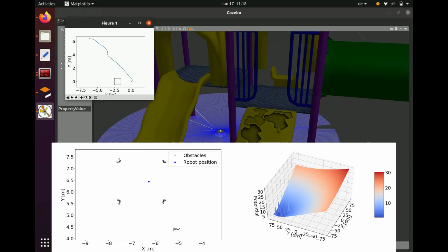It finished. Here is the last drawn potential field. You can see where the 4 poles surrounding the robot are inside the potential field. As you can see, even with a very basic implementation of the potential field method, the robot is able to avoid obstacles and reach its goal in a rather easy environment.